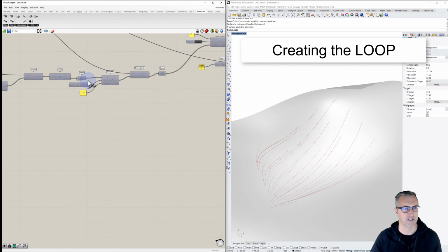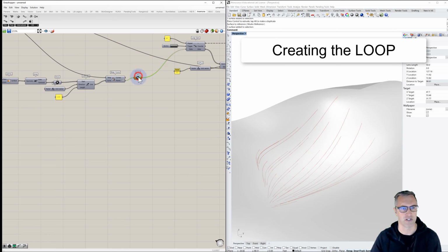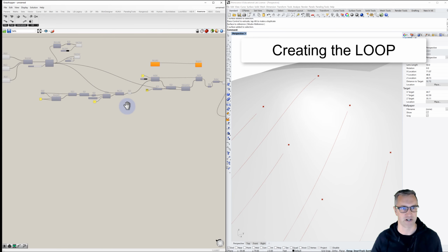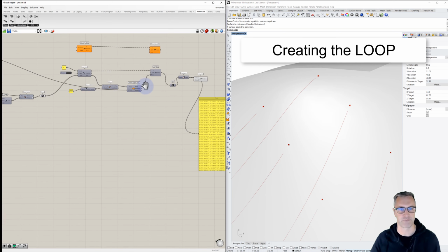Let's go back. I just want to also turn on something that was a little off when I did this earlier that I didn't like. We can see our starting points where we get the intersection between our vertical lines and our patch surface. We can see that the starting point is actually one element in the loop that's being left off. There's a way we can work through and add in this extra bit of that line so that we go directly from this first point into our loop from there. I'm going to leave that turned on for a second.